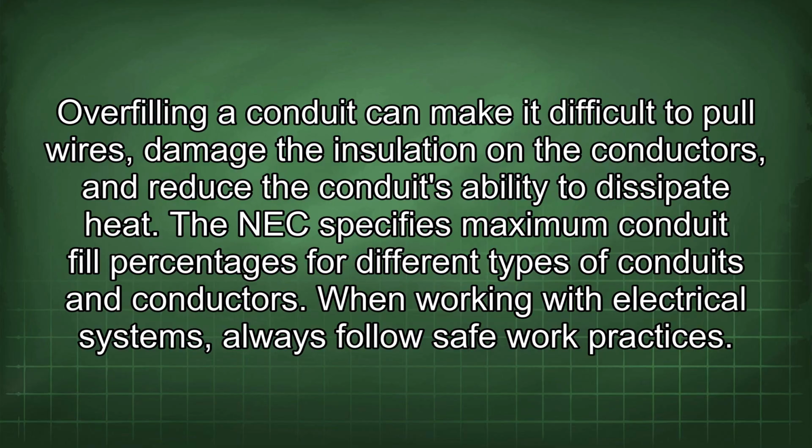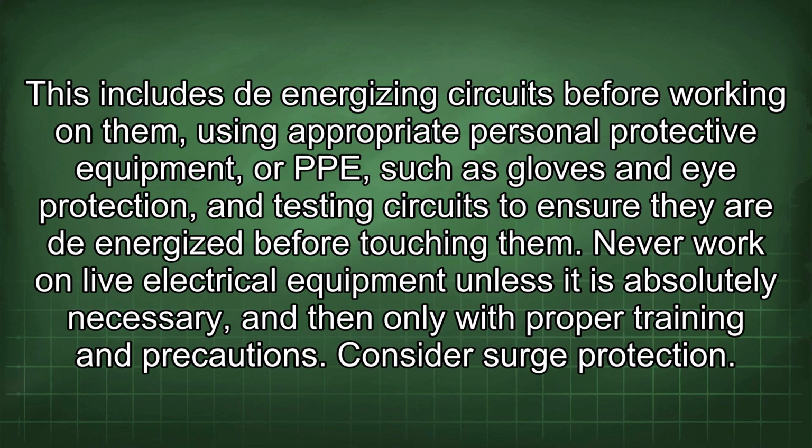When working with electrical systems, always follow safe work practices. This includes de-energizing circuits before working on them, using appropriate personal protective equipment, or PPE, such as gloves and eye protection, and testing circuits to ensure they are de-energized before touching them. Never work on live electrical equipment unless it is absolutely necessary, and then only with proper training and precautions.